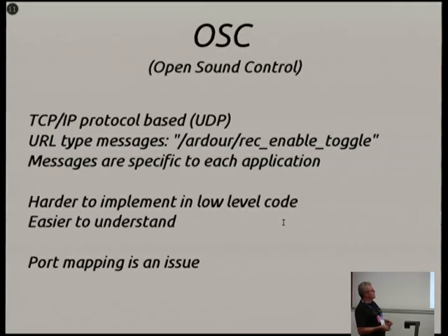An application can say, these are my standard set of interfaces, and it's not going to clash with anybody else's, hopefully. If you're writing at the microcontroller level, of course, this becomes a lot harder because you are doing a lot more work. You've pretty much got to store 20 bytes before you can even make a decision about what you're doing. You've got to have a whole TCP/IP stack sitting on your chip. So for that small microcontroller stuff, it's not as great from a programming point of view. Port mapping is still an issue because everybody picks their own port. From an automated point of view, where you want a whole bunch of outboard kit to automatically connect and know what it's talking to, there's still a lot of mapping and hacking around that you've got to do.